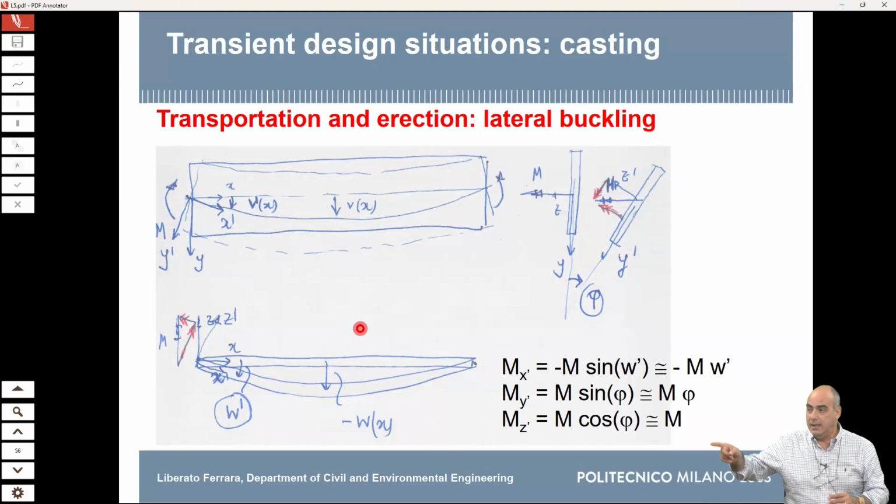And in the slides that the professor showed this morning, with respect to earthquake design, one of the failure modes was exactly because there was no compatibility of the deformation between the lateral system and the gravity loads. If you deform laterally too much, your column will do like this, and your gravity load continues to be here, and at a certain point, it falls down because of this.